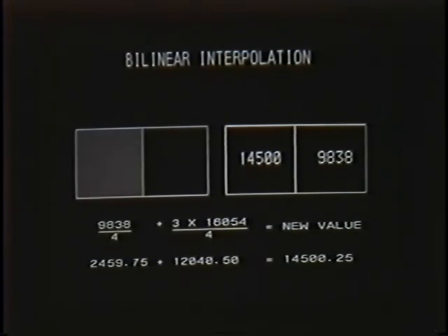If we perform this same calculation to every pixel in the image, we will cause the whole image to appear as if it moved a quarter of a pixel to the left. Let's watch this happen. Here we see the image before the approximated shift, and this is the image after the shift. If we want, we can continue to recalculate the interpolations over and over to approximate drift.